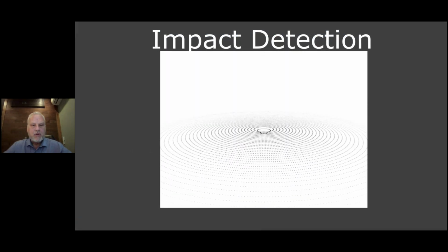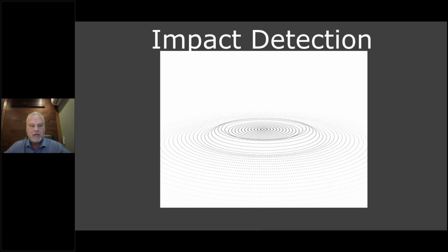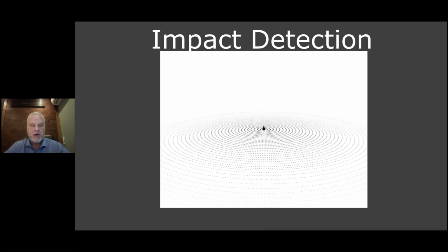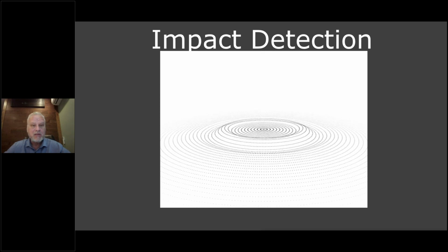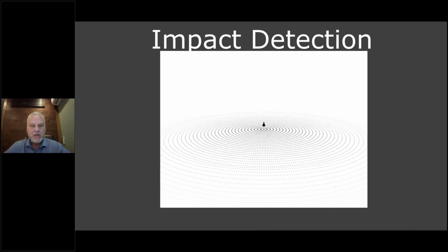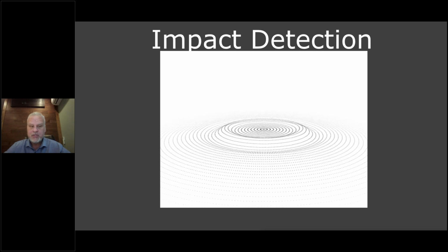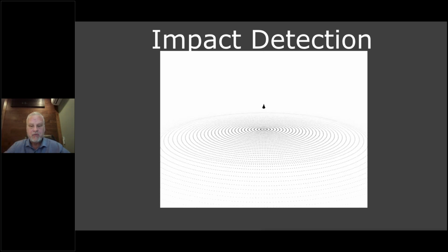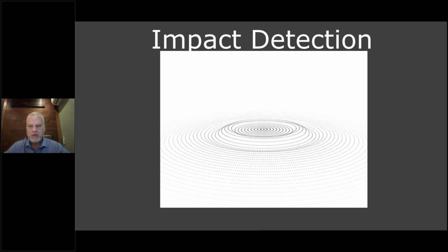All right, we're going to move directly into probably the biggest part of this presentation, which is impact detection. This is kind of our last and probably becoming more and more important detection method for helping us in slow speed. Obviously, it helps us in high speed machinery as well. It doesn't solve everything, but it certainly gives us a better view into what's going on in slow speed machines. And again, we just recently had a case where we had a large gearbox, and the only indicator we had of failure was the impact detection tool. There was nothing, and there were no indications in the regular high range or low range spectrum.